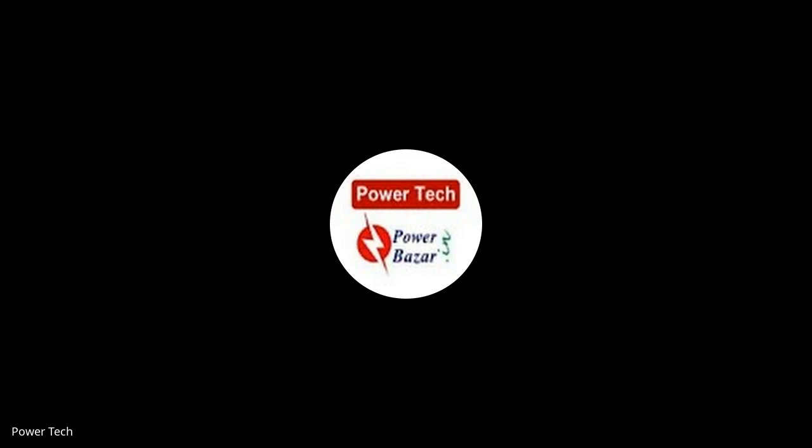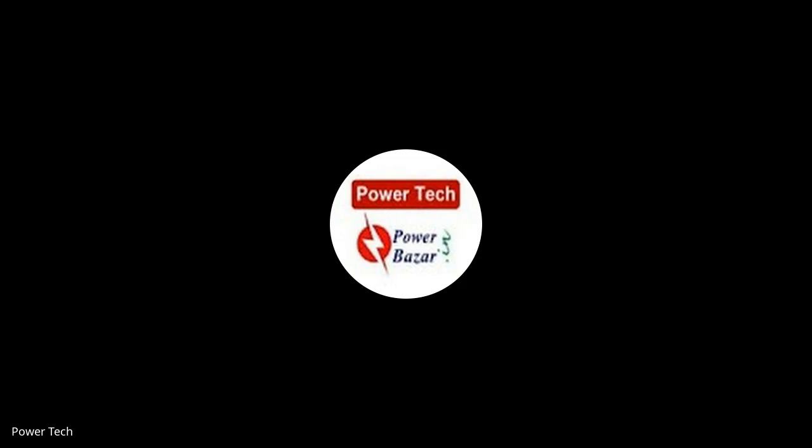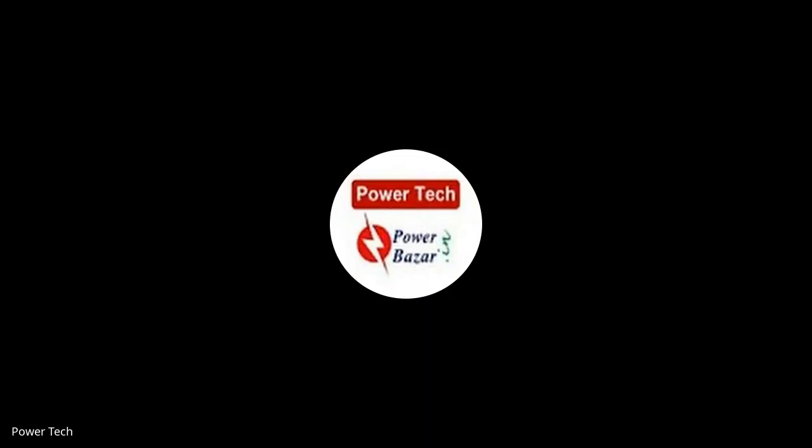Then Santosh Das ji has also asked, how to take care of over voltage in capacitor design, and what is the life of vacuum contactor in case of ST-FEFC panel? Two questions. First question: how to take care of over voltage in capacitor design? First of all, the capacitors are designed for a particular voltage, and suppose it is 440, as I said, we design for 525.